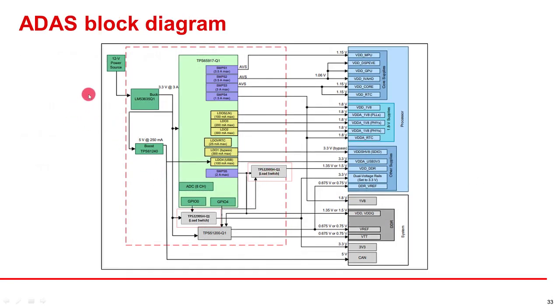As you can see, the battery feeds into the buck converter, which powers the PMIC, and an additional TPS22995H-Q1. Each load switch ON pin is controlled through either GPIO 0 or GPIO 4, which could be programmed by the PMIC to enable after the required rails are enabled first.